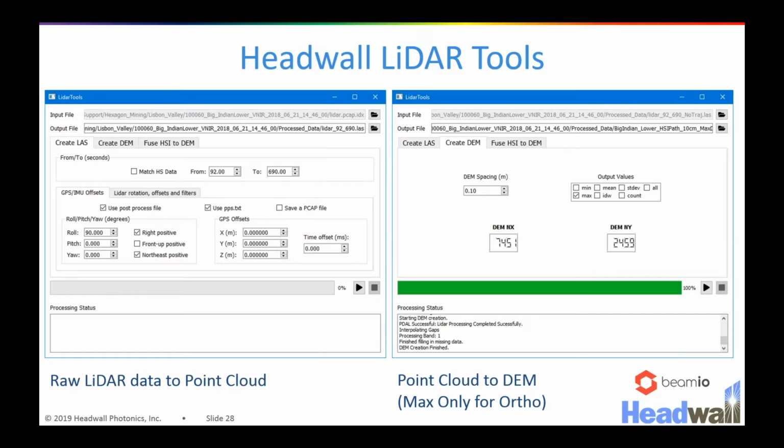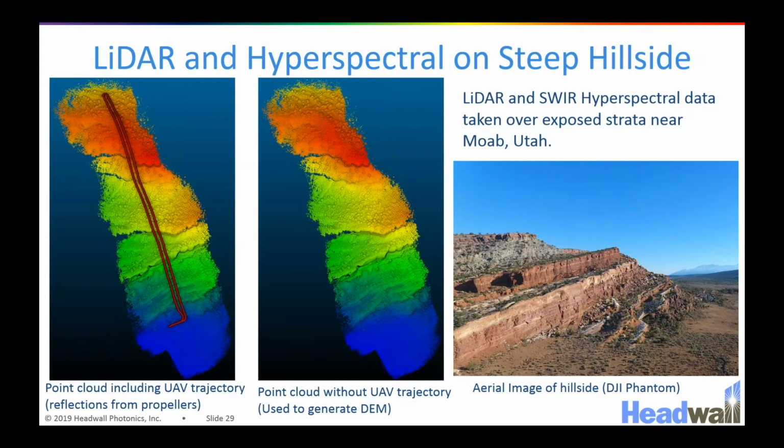And your standard digital elevation models available through the USGS or other online sources give you about 30-meter resolution or so, where if you're taking a ground sampling distance of 5 to 7 centimeters, you're often going to want better than 30-meter resolution in those digital elevation models. And so using the LiDAR data, now we have a 3D map of the scene that we just scanned over, so we can create our own much higher resolution digital elevation model that includes everything in the scene and stuff that might have been added since the last survey was taken, and give a much better orthorectification.